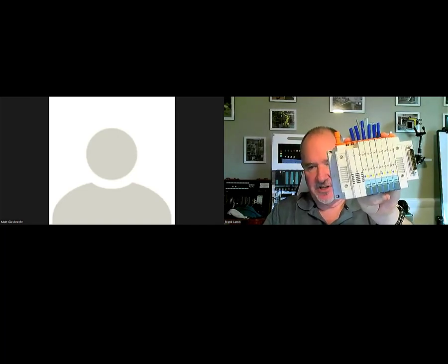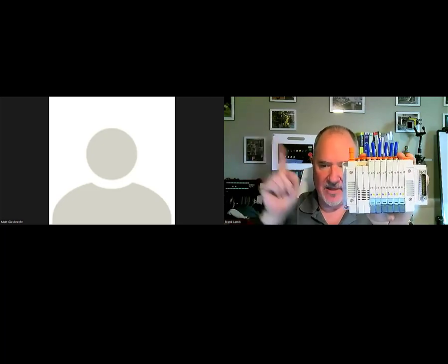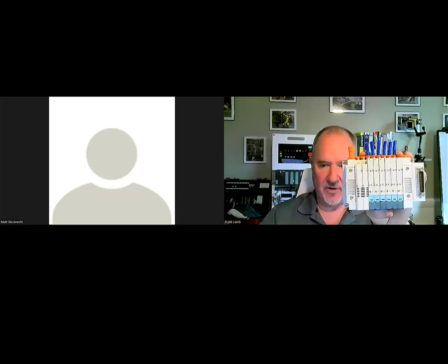This is the valve bank, let's see, that I was showing you before. There's some of the explanations of this in the book also. These little actuators here, one energizes one of the ports, they're manual actuators, and the other one energizes the other port. So if I take a little probe or something, I can push those and make air come out of the A or the B port, even if I don't have power on the solenoid valve itself. So down here, you can see these are the actual solenoids, right, on the end of the valve. And then this is the manifold where all the air comes out. And this one was on that old machine I was talking about.